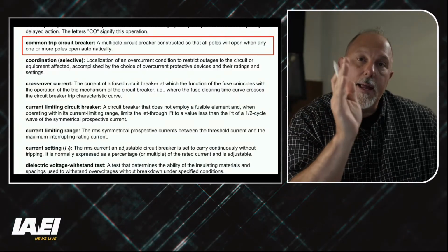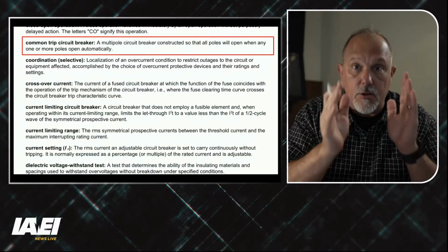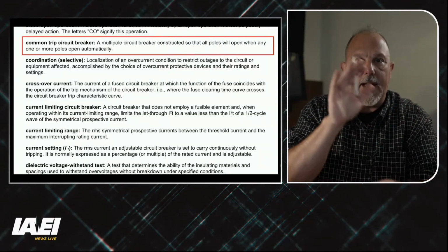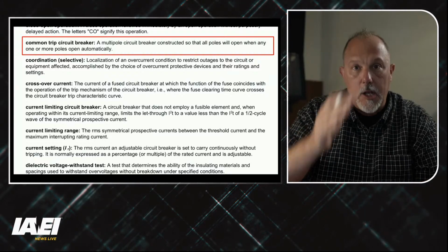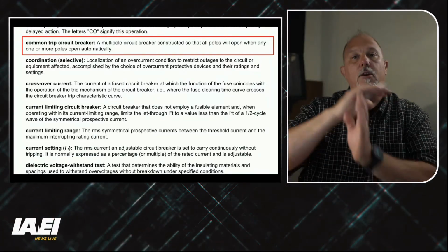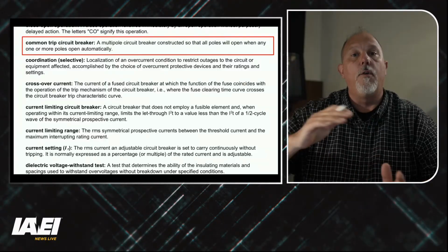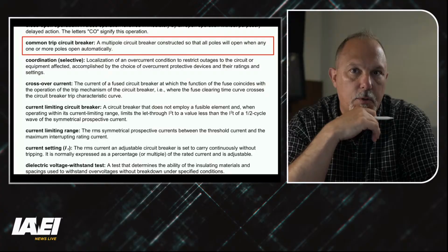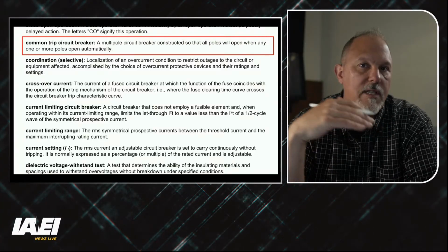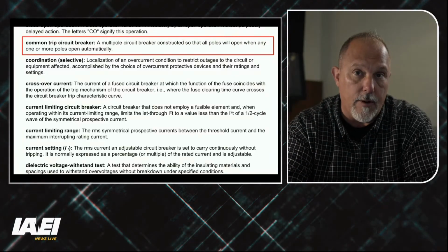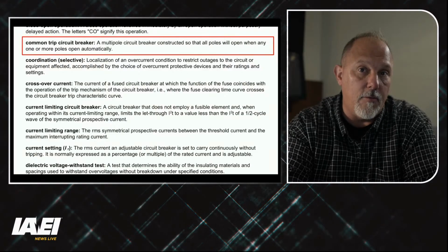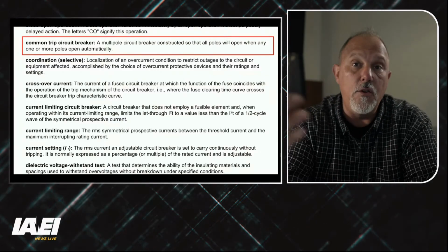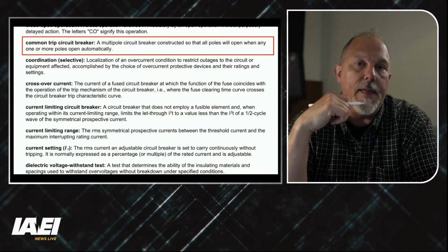So I'm relying on the molded case circuit breaker, or any circuit breaker, the contacts, to open on the lower fault currents, and I'm relying on the fuse for the higher fault currents. I know there are power circuit breakers designed with, say, a 200,000 amp interrupting rating, and they get that rating because of the limiter or the fuse that's buried inside that device.